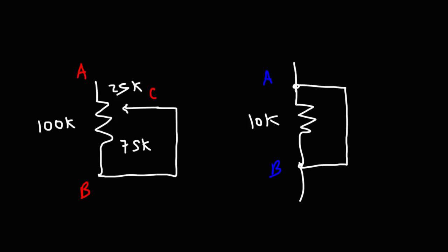When electrons enter this circuit, they don't want to flow through the resistor. They're going to flow through this conductor because there's less resistance, and so the wire bypasses the resistor. The resistance between A and B is now 0 ohms due to the wire that's connected across the resistor. So once we connect B and C, the resistance of B and C is wiped out.